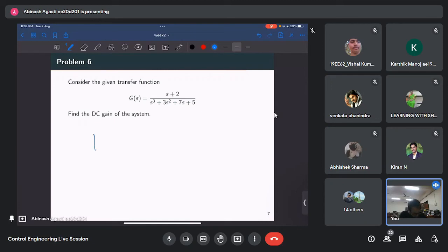So I have a system. I give a DC signal, and what is a DC signal? It is basically a constant time signal, that does not fluctuate, no oscillations, nothing. So if I have a DC signal, then how many times is the output amplified? The best way is to take u of t, which is a one-value DC signal, a DC signal of amplitude 1. When I give it to the system, what is the steady state output of the system?